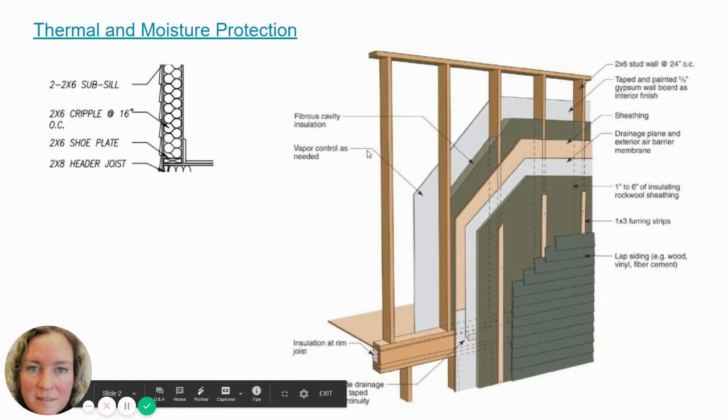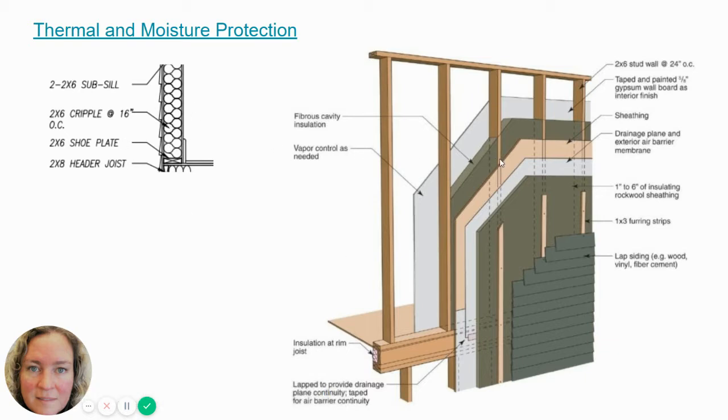It's actually improved from the original, where usually we used batt insulation on the inside, which is very poor quality insulation. We didn't have the extra layer of insulation on the outside in the buildings we built in the 70s and 80s. And we put studs in some cases too close together, so it reduced the number of places that we could fill in insulation.